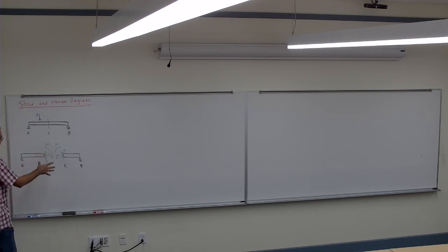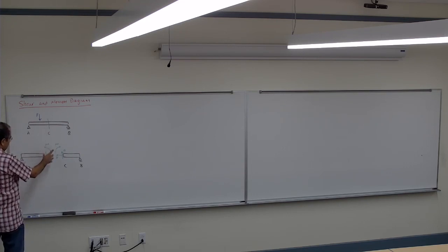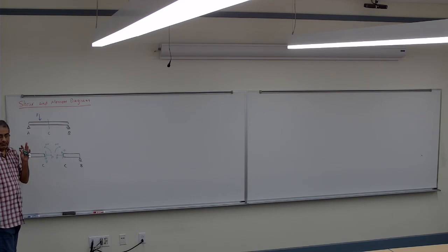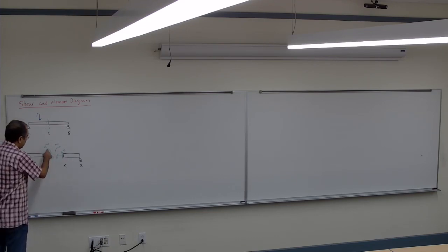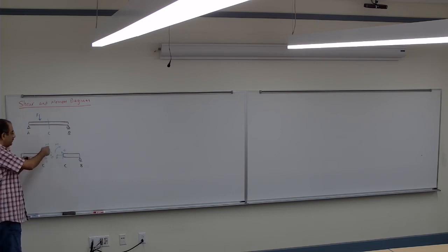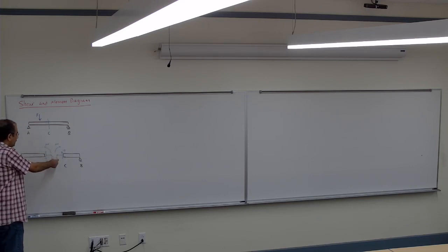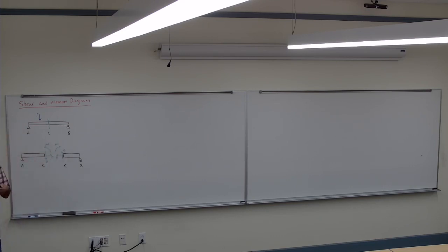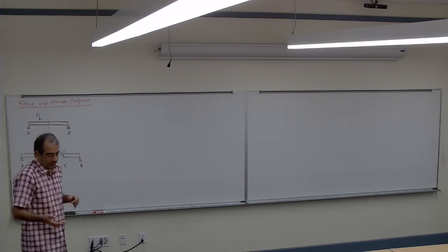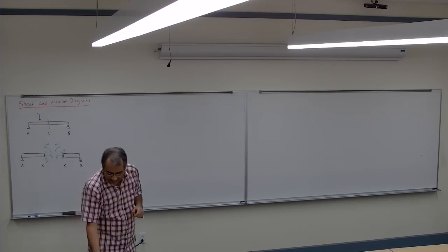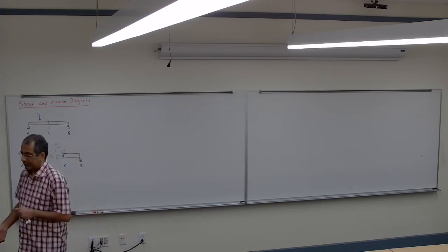The entire point is that we want to design for the bending. So we want to find the moment diagram, but usually to find the moment diagram, you have to find the shear diagram, and then from there find the moment diagram. So we're going to learn these two. At the moment, we don't care about the axial load, so we are going to leave it for now. Let's start with a simple example and show you how we do that.